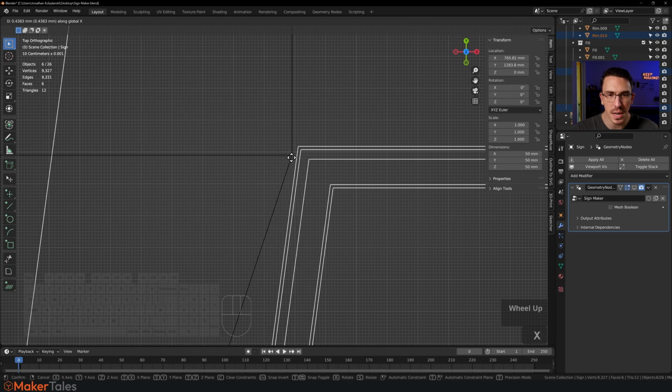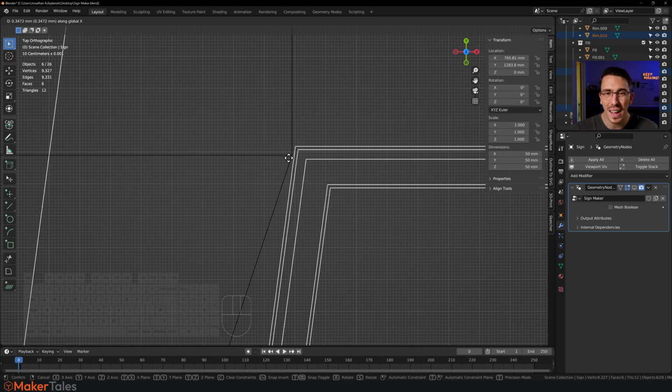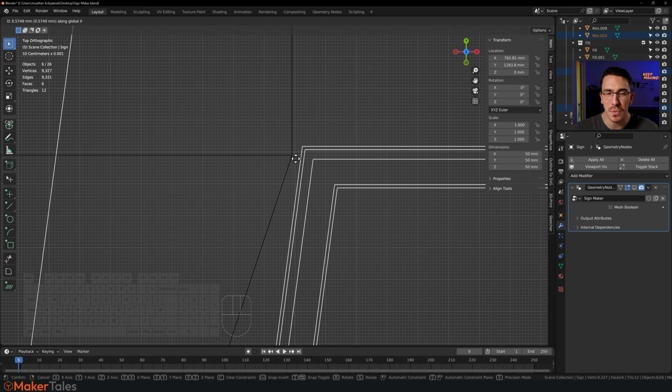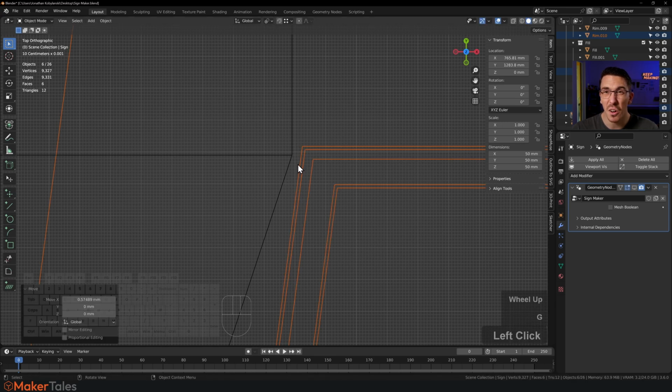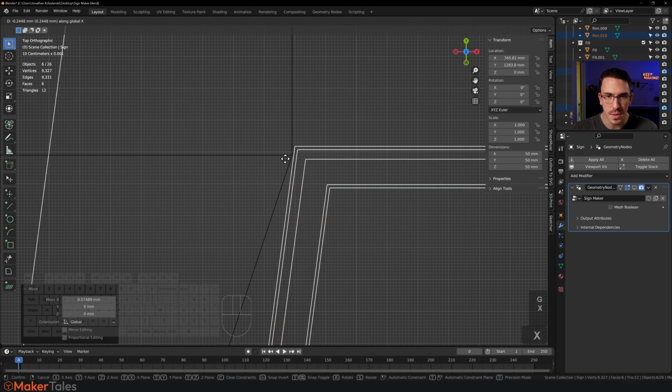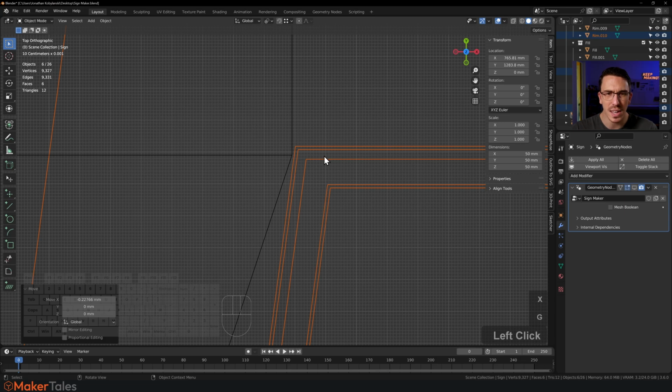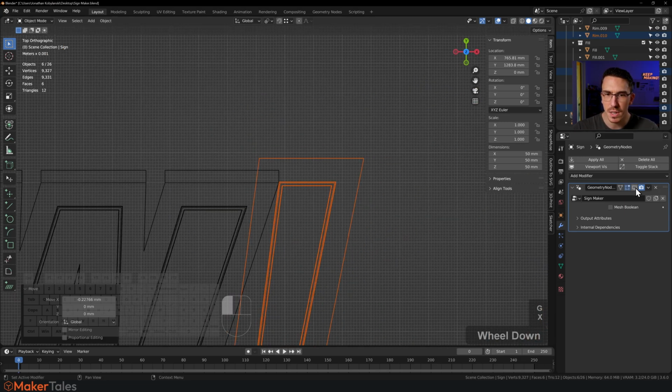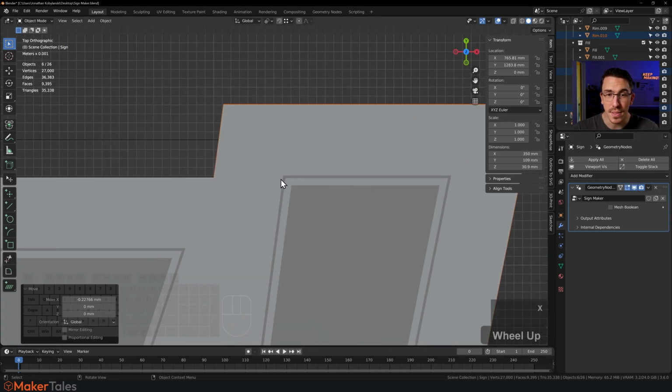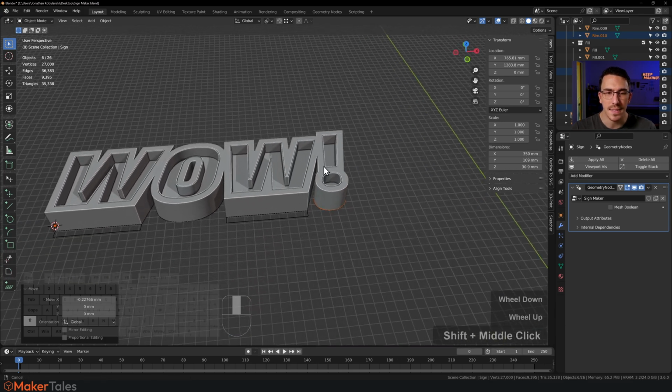I'm just going to pull it out, maybe I'll give it a little bit more so that when I'm 3D printing, it doesn't cut it off right there. It's up to you. Depends where you're going to have the trim. So I'm just going to leave that probably somewhere around there. I'm pretty happy with how that's looking there. Yep. And now I can just turn this back on, and that will be that sorted, no problem at all. And this is now ready to go.